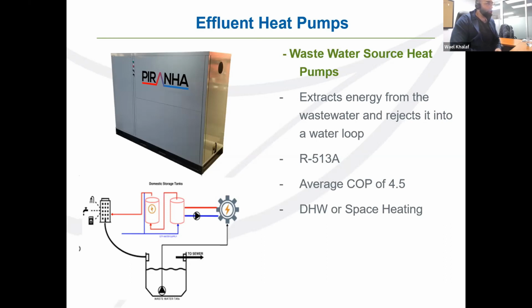The storage tanks are designed to basically not hold the wastewater, but slow down its flow. So, say you have an incoming flow, it goes through a big tank, but that tank also has a gravity drain coming out of it. So, basically, wastewater comes in, slows down in this tank, and then it's also letting the wastewater leave on the other side.